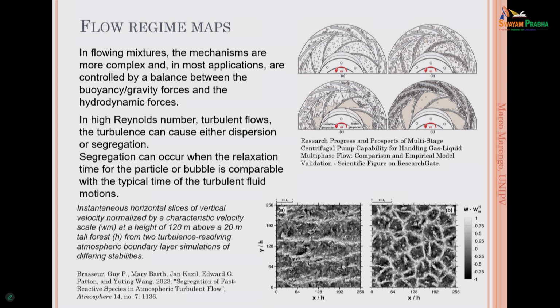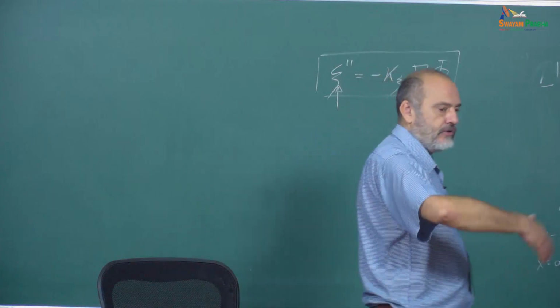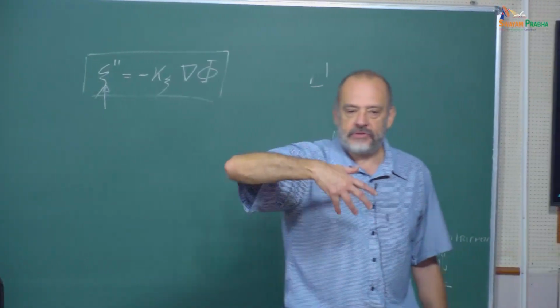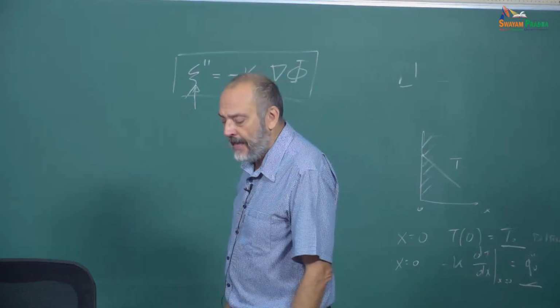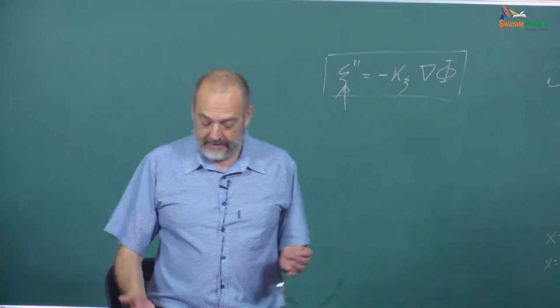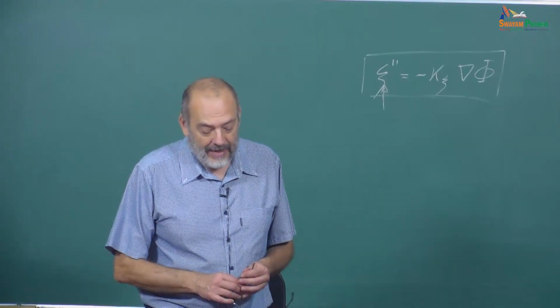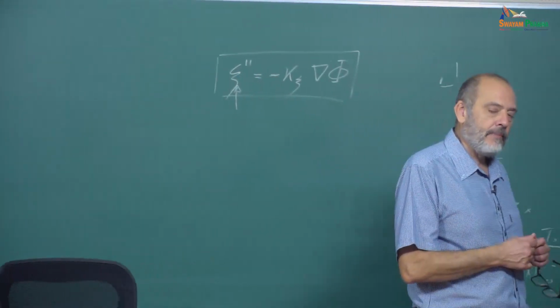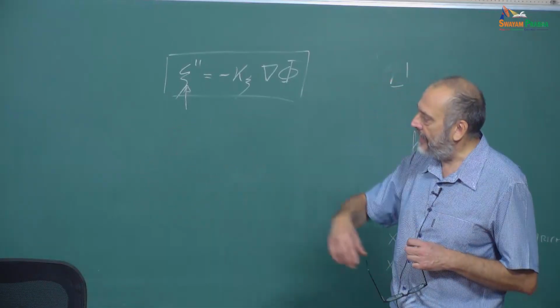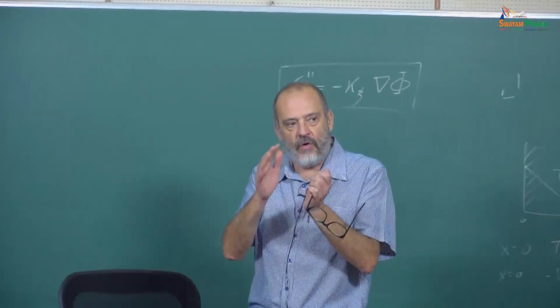Atmosphere is a multiphase flow, huh? Sorry, a multiphase system. It's quite complex, very complex, okay, with a lot of different things. And we spoke about something that is rotating, where the solid particles go to the wall. The bubbles are going to build structures because the density is lower than the continuum phase. And when we have characteristics like in the atmosphere, we are dealing with turbulence because the dimension is very big, okay? So in this case, what is happening, we have structures like that. So we are forming clustering of the dispersed phase.